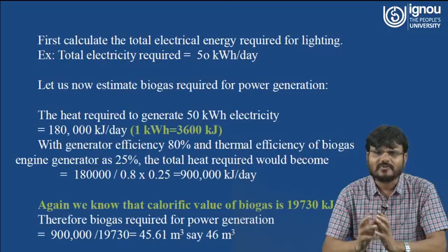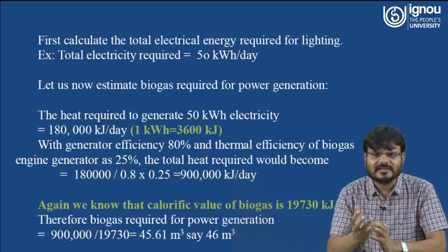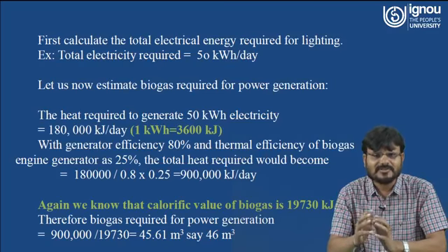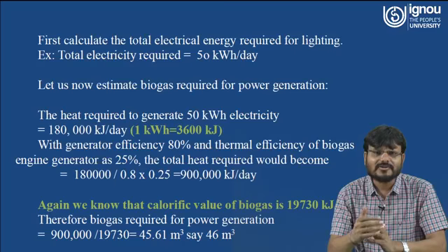You know the wattage of all the appliances, and you know how much time you will use those appliances. You multiply the wattage rating of each appliance by the time of use, so it will be watt hour, right? Now you divide by 1000, so it will be in kilowatt hour. This is how you can convert to the number of electrical units required in your home.